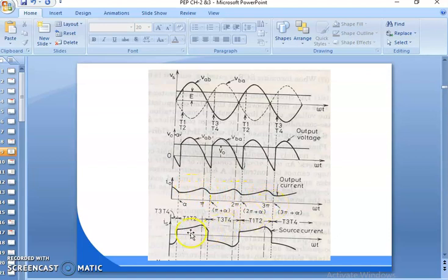And then come to the IS, the current across the thyristors. See that here the IS current arises only when T1 T2 are in on state. Due to the T1 T2 on state, the current portion will be like this, and this one will be when T3 T4 are on in the negative cycle period.